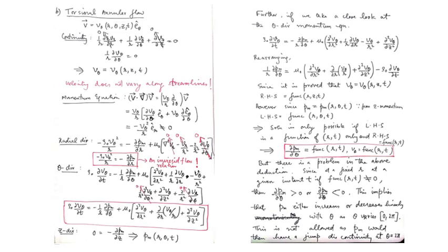So if I consider the theta direction equation and rearrange the terms, one thing we can observe from this rearranged equation is that on the left we have the motion pressure derivative with respect to theta, right? Since pm is, up till now, a function of r, theta and t, the left hand side can be a function of r, theta and t. But what is on the right hand side? We have only velocity v theta derivatives, right?